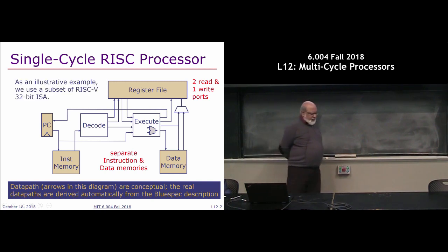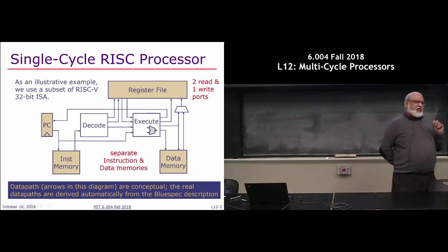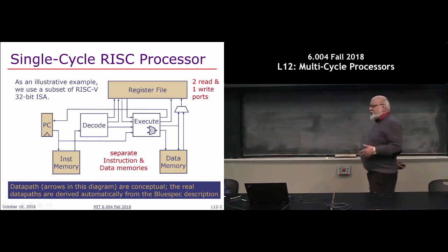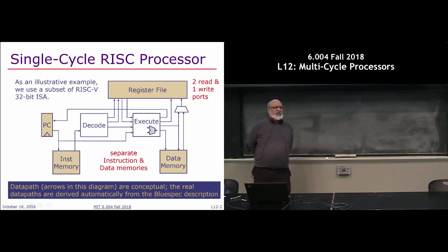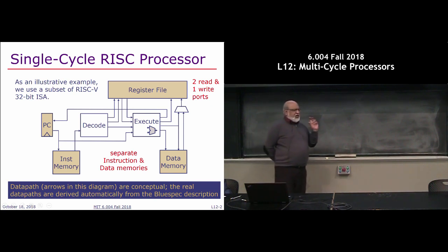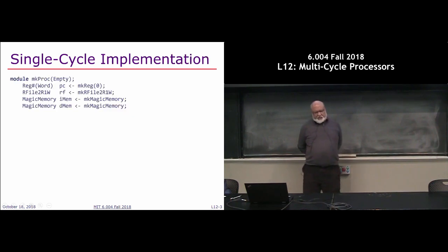The example we have been using is RISC-V, and we are just leaving out a few instructions because they are very straightforward to implement, but we just didn't want to increase the work. These instructions all have to do with reading half words or updating half words of memory, because our memory structure is loads and stores, and we always think in terms of words when we operate on the memory.